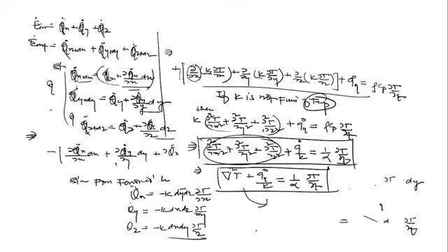So whenever you want to use this equation, you should be very attentive that there are two assumptions I have considered: that is, uniform area and k is not a function of temperature. Then only you can use this equation, and Cartesian coordinate system obviously. Okay.